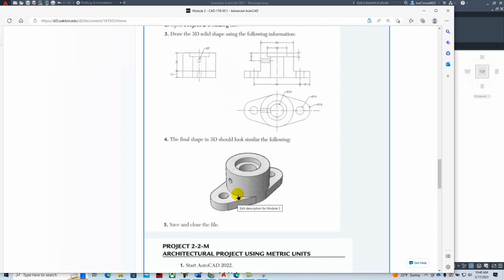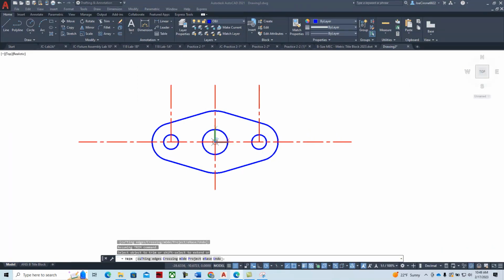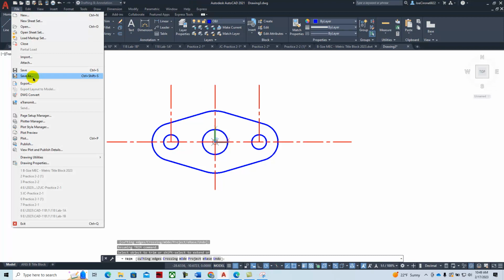Now, press pull is a more advanced command, because press pull actually will create a macro that creates a boundary shape, a closed polyline shape, and then applies an extrusion so that you get a solid rather than a surface. And I'll show you what I mean. So if we do a quick save in case we make any errors.